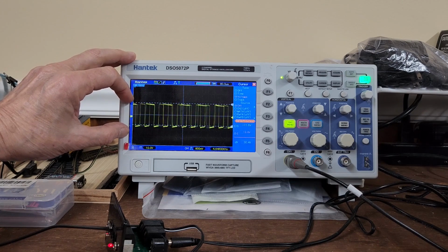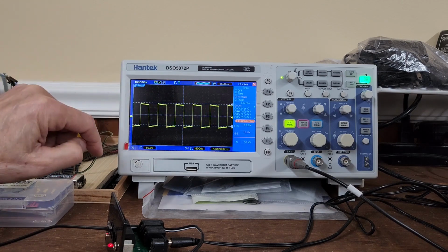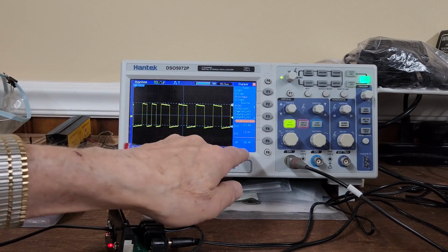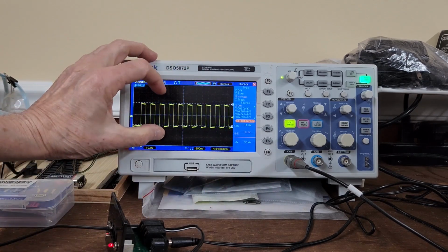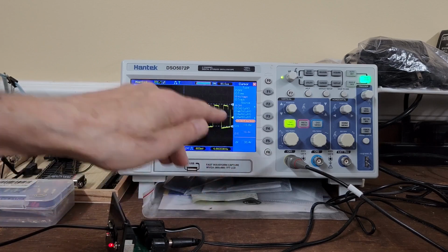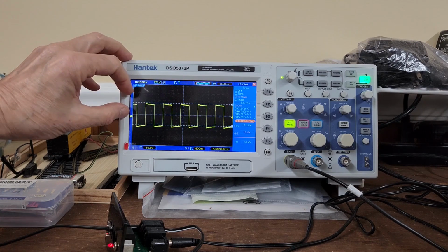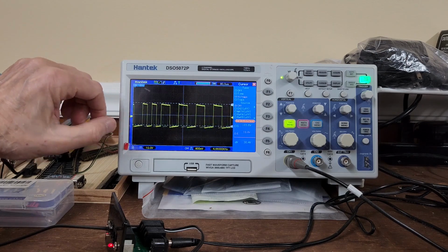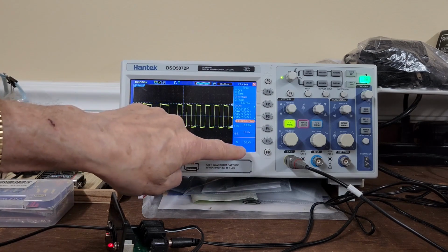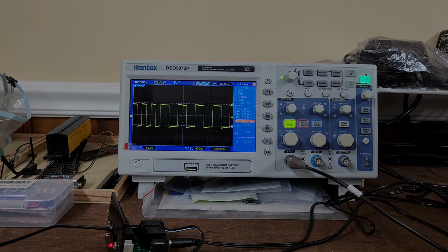They are symmetrical about the ground, positive and negative, and the total voltage differential peak to peak is 30.4 volts measured by the scope. So basically that means the power cab uses about a 15 volt DC source, and that 15 volts plus and 15 volts minus is creating a differential voltage of about 30 volts.